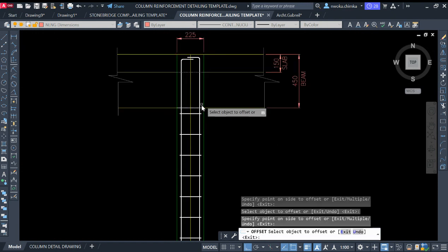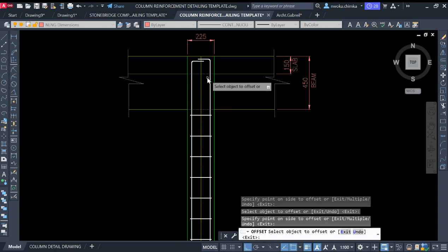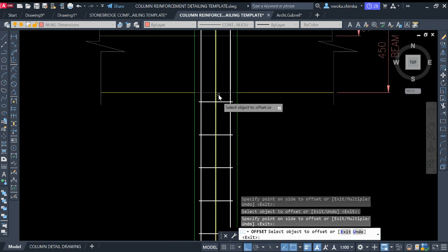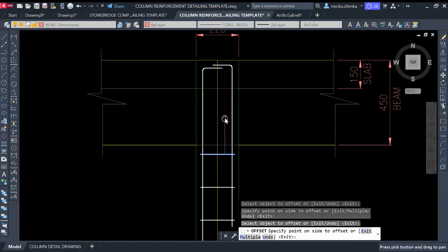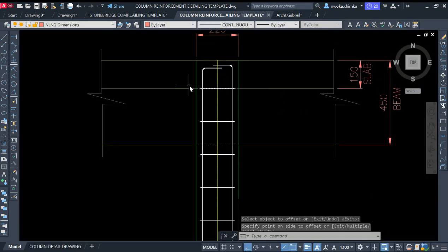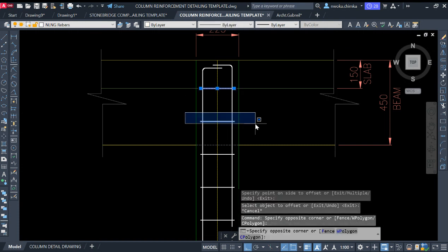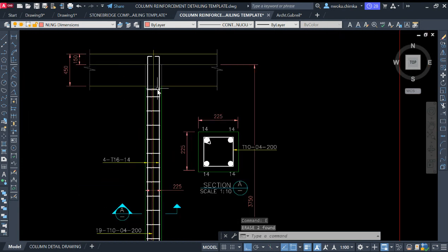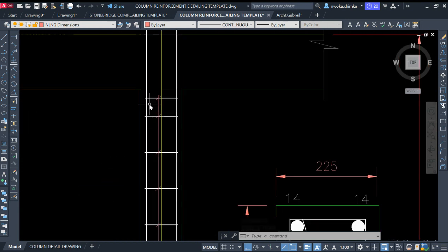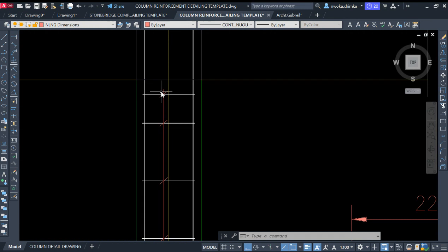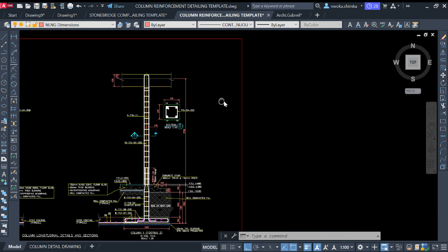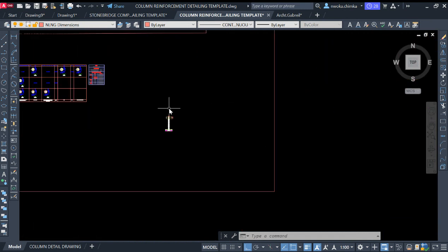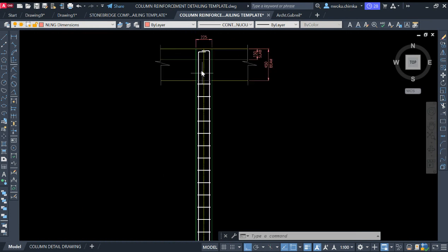So right now we just have to stop here, because link reinforcement does not enter into the beam. The beam reinforcement we have to hold this column here. So we have to stop directly at this point. You don't have to go into the beam to start showing the links. This is wrong, so you just remove this and stop directly at the beam edge as you can see here. Also, if you look at our go by, our sample, the link stops directly on this point. So right now what I'll do is show this link. So we have shown our reinforcement also for the column.